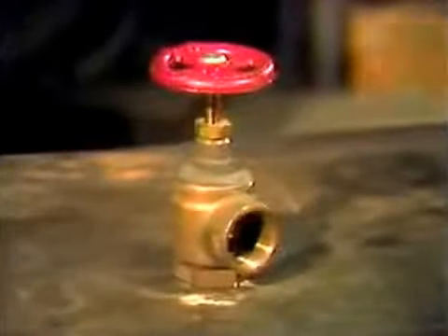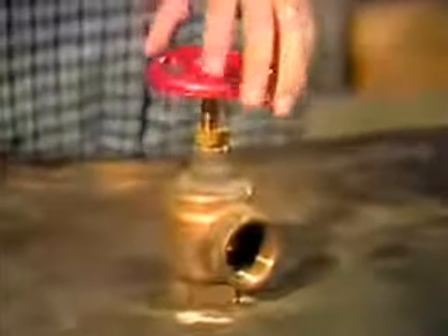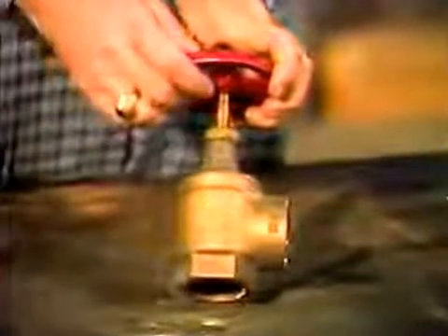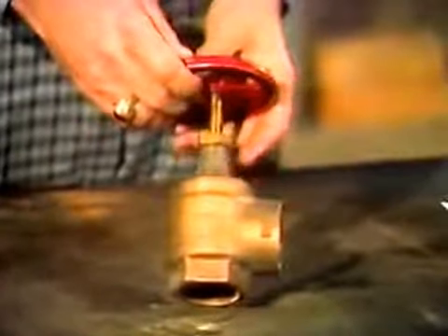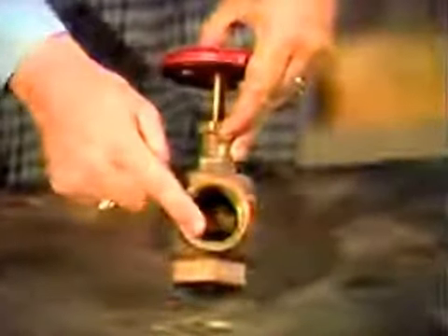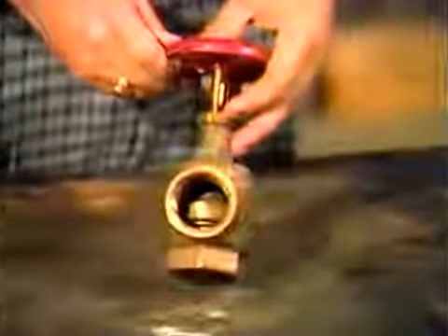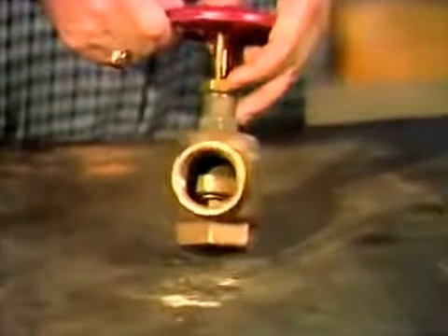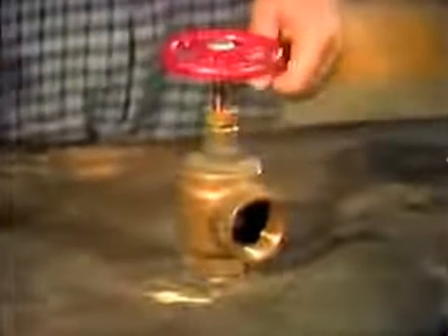Another body type is the angled globe valve. This design helps to eliminate the need for adding elbows to change the direction of flow, thus reducing the number of joints. The fewer the number of joints, the fewer points where leakage can occur. Now, both of these surfaces are built to provide a tighter seal for positive seating than is found on a typical gate valve. The shape and arrangement of the disc on a globe valve is varied depending on the type of service it's designed for.